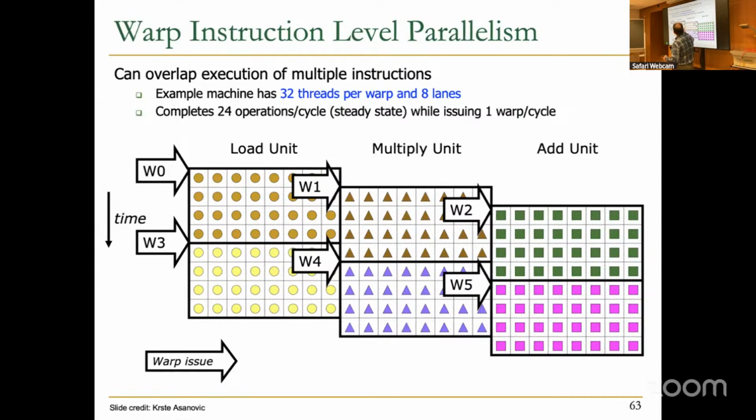And here you can see that if your SIMD engine is, for example, 8 lanes wide, your warp is 32 threads. You assign 8 threads and run them in parallel in 8 processing elements, but then you need to pipeline the rest of it. So you need to run 4 iterations of one 32-thread warp in order to finish the execution of warp 0. So that's the part where you are combining array processor and vector processor together.